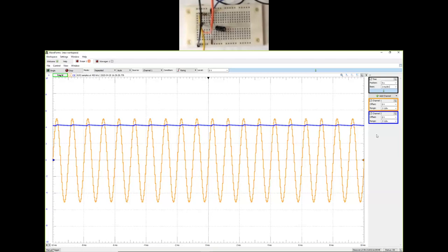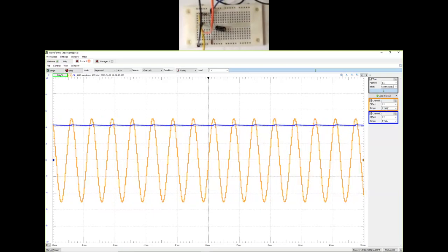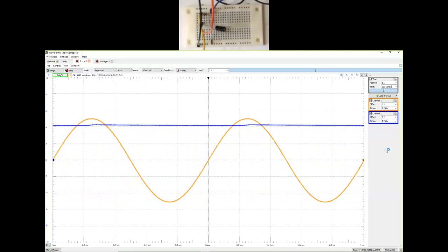But if I was just trying to compare the effectiveness of my DC, in that case, I can leave my Y ranges, meaning volts per division, as is, but instead of looking at 2 milliseconds per division, I look at say 200 microseconds per division. So I'm essentially zooming in only on the x-axis. I'm leaving the volts per division on the y-axis as is.